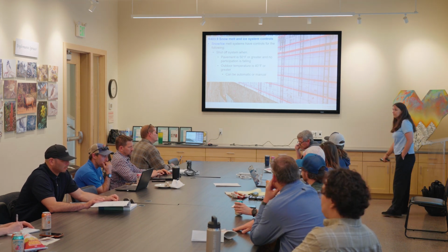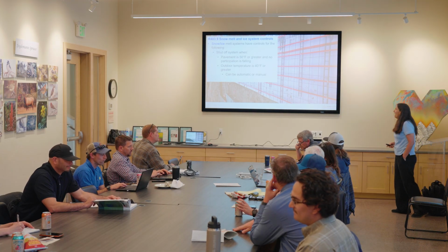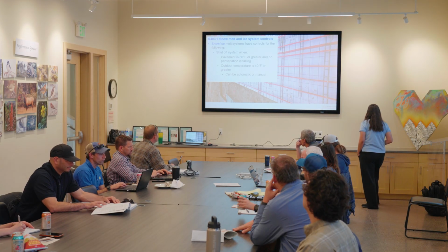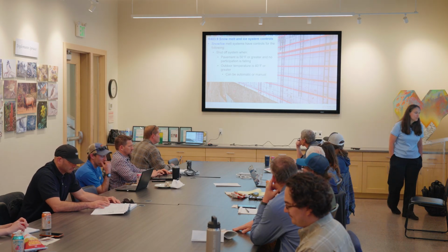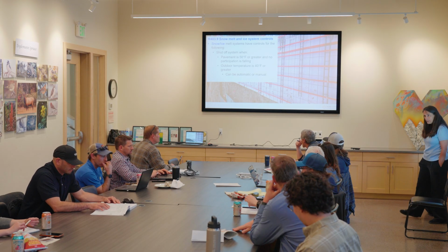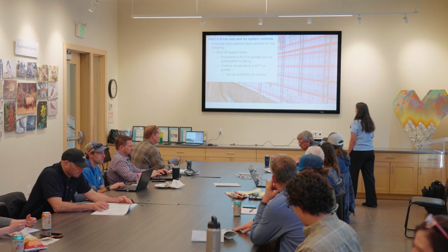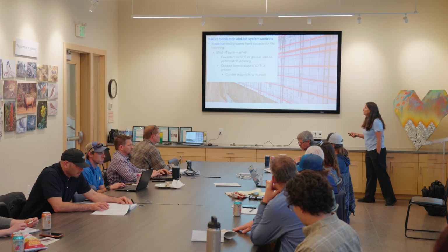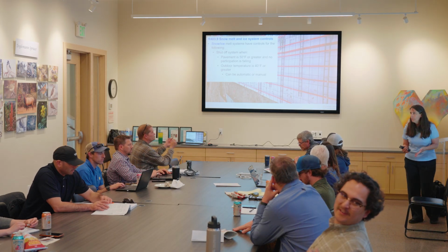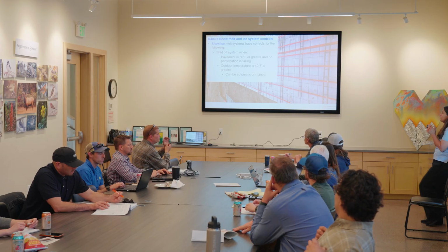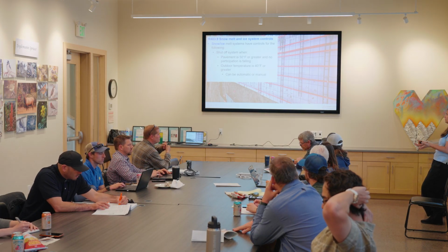Okay. Snowmelt systems. Anybody have snowmelt systems here? All right, so if we have a snowmelt system, the energy code doesn't say you can't do it. What it does say is you will need to have controls on it. That control needs to basically shut everything down when the pavement is 50 degrees or warmer and we don't have any precipitation falling and the outside temperature is at least 40 degrees.